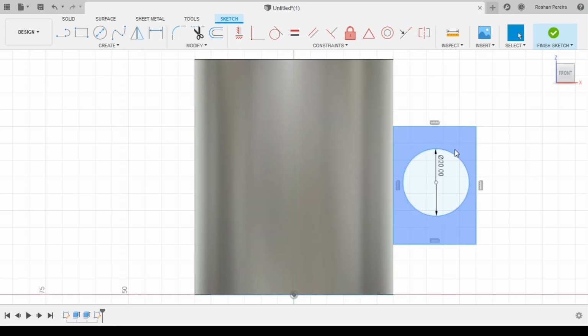At this point, we can see that the rectangle that I have drawn has pointed edges. So to make these edges flat or rounded, we want to use the fillet tool. What the fillet tool does, it's in the sketch, and you find it here in the modify. When you click the fillet and it's activated, you have to choose the 2 sides that you want to use for the fillet. So I want to use this one side and this one side. It creates an automatic fillet. You can choose the radius of the fillet, but I will keep it to its default.